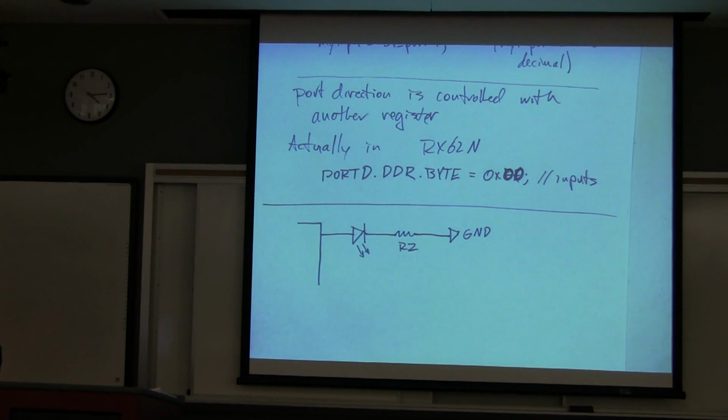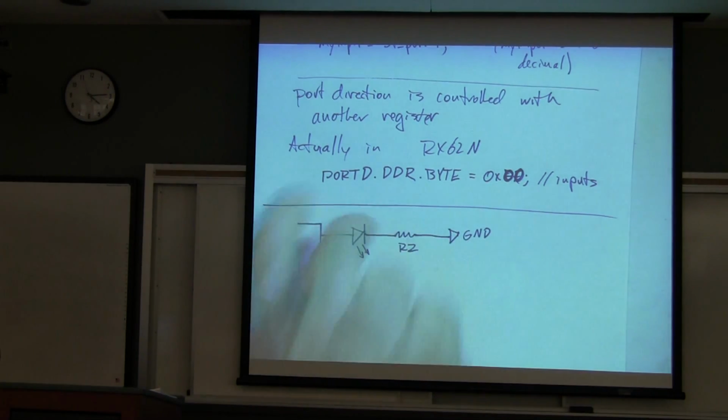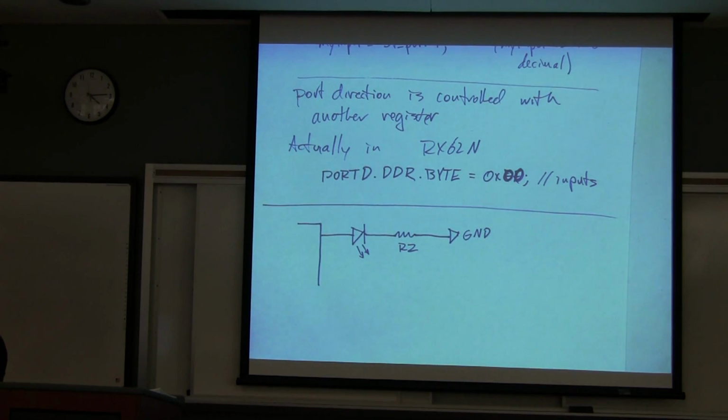By the way, should you have the resistor on this side of the diode or on the other side of the diode? I've always asked people that. Does it matter? Technically it doesn't, but it's usually better to have the resistor on the 0 volt side.